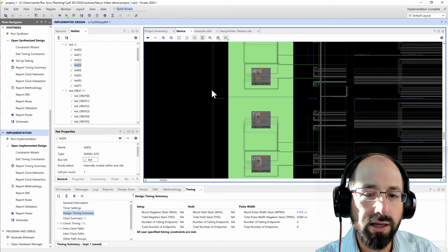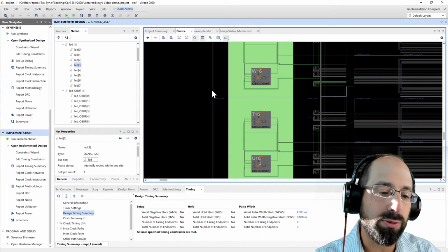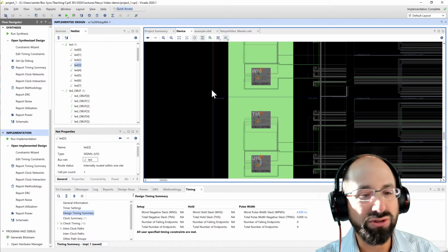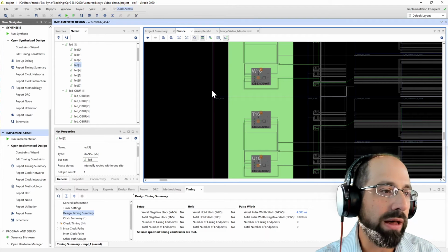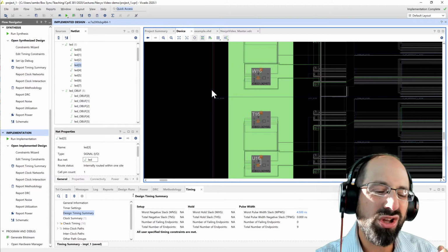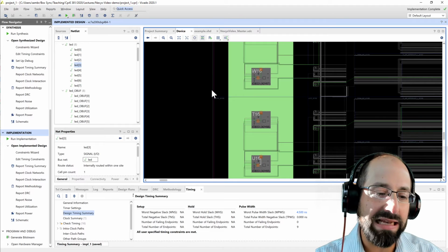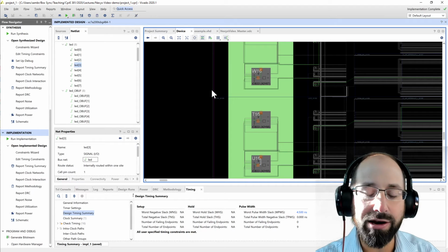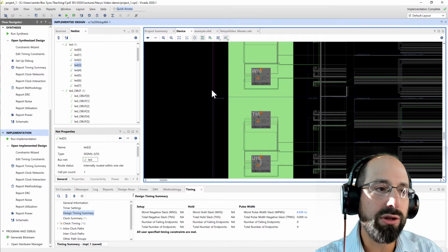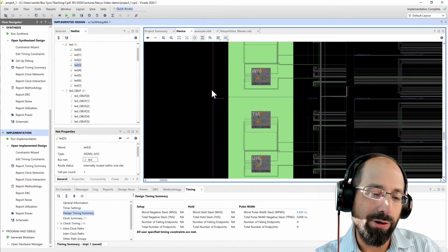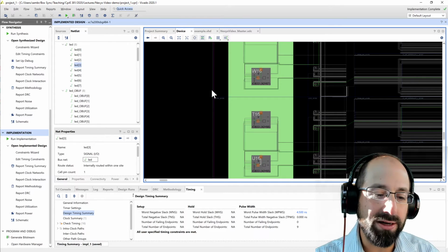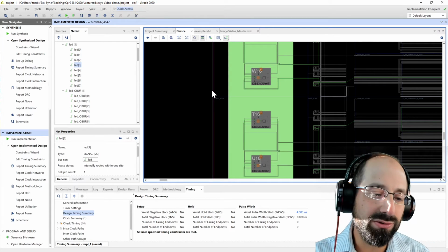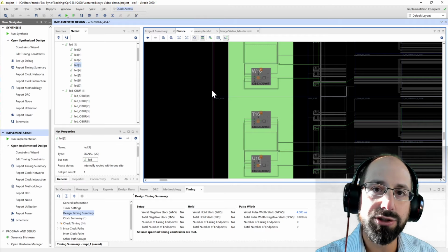Those algorithms, and I've admitted not being a true expert in those algorithms. Professor Chu would be the right person to chat with about those. They're all heuristics. They're all kind of just effort-based algorithms. There's no exact algorithms for getting the best possible layout on a device. So you'll see algorithms, and they'll have parameters such as how hard do you want to try? How many iterations do you want to try before giving up? And that can also directly influence how long it takes to get to a result.